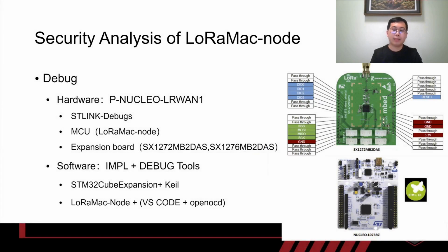After having the ability to send malicious radio packets, we can select some development boards as the environment for local LoRa node debugging. We can choose the NUCLEO-L152RE development board as the test equipment, which provides an MCU, expansion boards, and ST-LINK. VS Code and OpenOCD are used to debug the software. This development board is very suitable for debugging the protocol stack and can help us quickly verify the vulnerability.